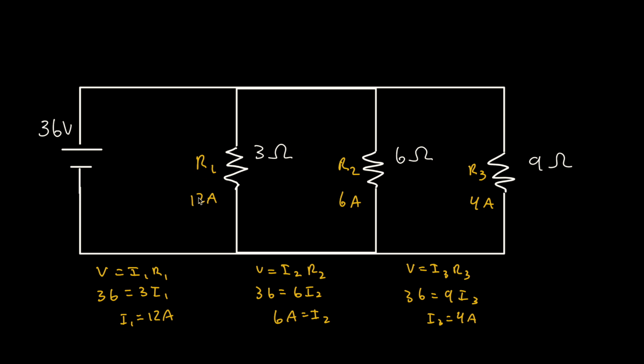And as you'll notice, as the amount of resistance increases, the amount of current flowing through these resistors is actually decreasing. So when we're talking about Ohm's law, we were saying that the relationship between current and resistance is inversely proportional. Or just for this example, it might be easier to see the fact that as we're increasing resistance, we are decreasing the amount of current that is flowing through these resistors.